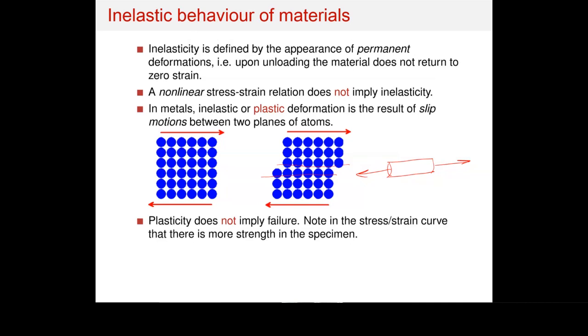I'm going to say inelastic here because I'm going to talk about situations where this is going to break altogether. So it's not just going to move or deform permanently, it's going to break. So for ductile material, this is going to move. For brittle material, this is going to break. So anything beyond the elastic range is going to be inelastic, so break or plastic.